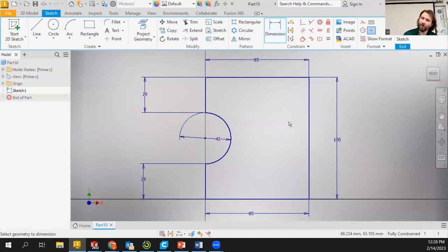And again, if you keep up with the dimensions that are needed as you're creating and continuing to manipulate the part, you can keep it fully constrained. So at the end, you're not having 27 dimensions to add to the sketch. That can be painful. Right. So just keep adding those as you're going through, dimensions or these other constraint tools that are here. We'll go more in depth into those with other videos as we move forward.